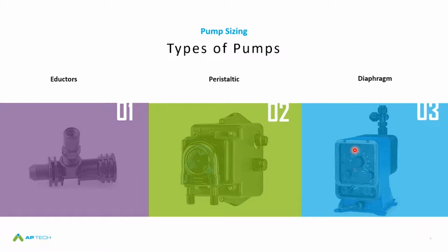The other variations of diaphragm pumps are degassing or gas-off heads, typically reserved for biocides, because oxidizing biocides and biocides in general can gas off, and what that can cause is an airlock inside of the pump head itself. And so once you have that airlock, you're no longer pumping chemistry. So it can be frustrating, but once the gas-off pumps came out, that was a great thing for them.